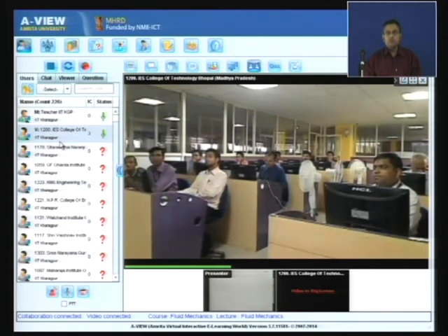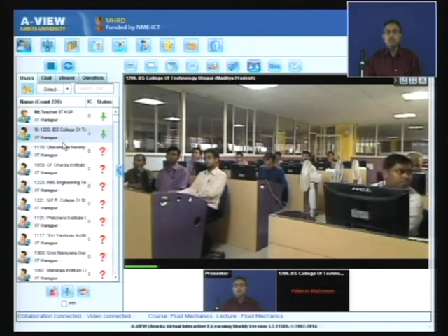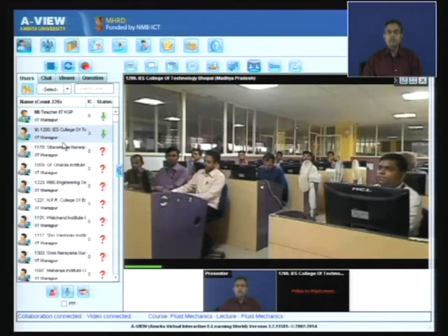So, for low Reynolds number you cannot use the boundary layer theory, because in the boundary layer theory you are assuming that the characteristic boundary layer thickness delta is much less than the characteristic length scale L. If delta is not much less than L, then this is not valid. So, you cannot use the boundary layer theory when the Reynolds number is small, although the concept of boundary layer is there. Remember that boundary layer concept and boundary layer theory are two different things.